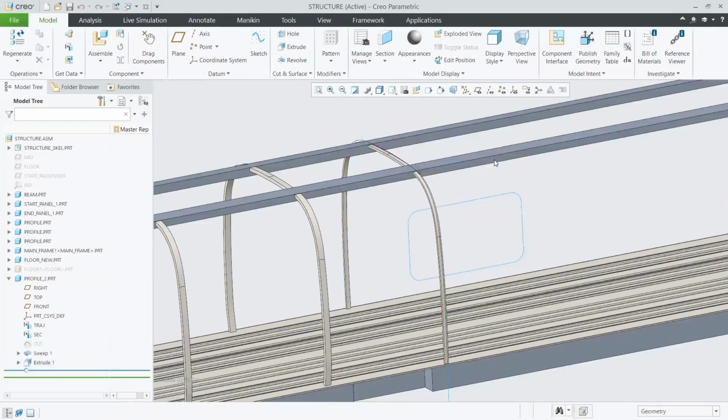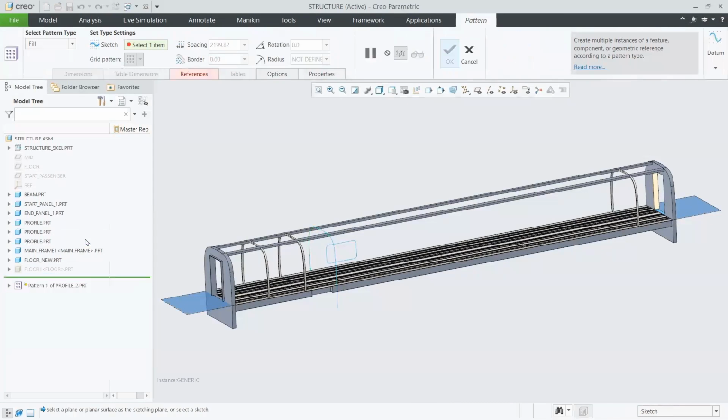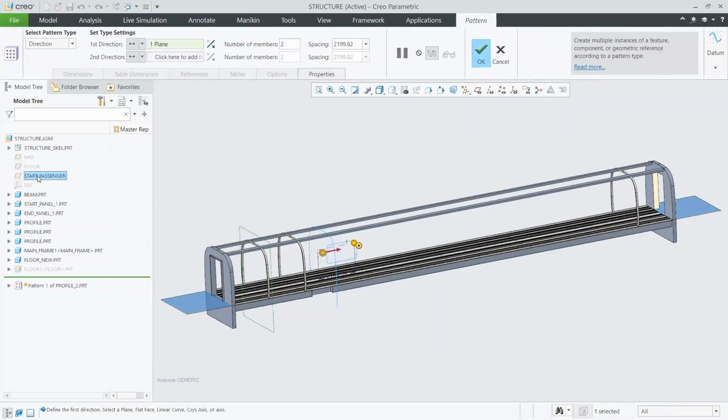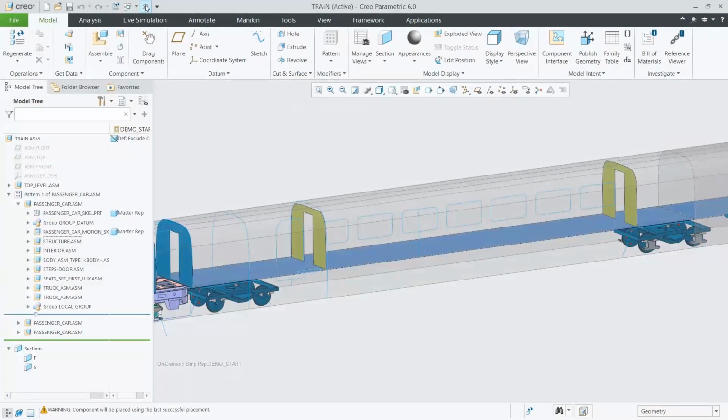But the idea is the master overall shape is controlled by that top level skeleton geometry. That's what advanced assembly is all about, making it easy to make connections, to control them. And then as we'll see here, as we go on through this demo, to change them. So now my one support structure I made looks good. We'll just apply it to the rest of them here. So now I've got my new hoops and they're set to the master geometry.